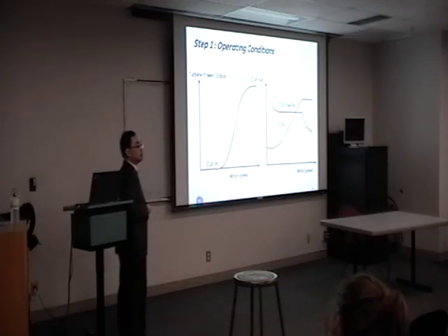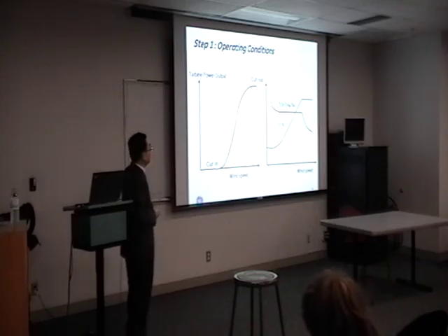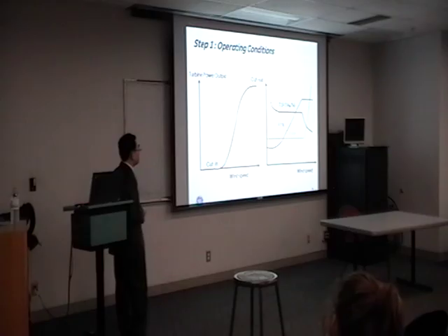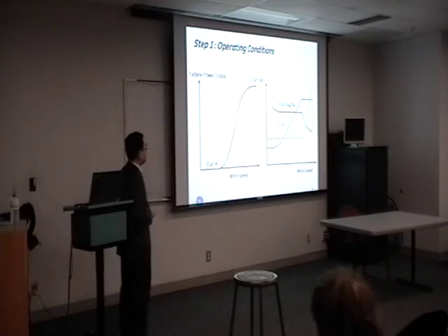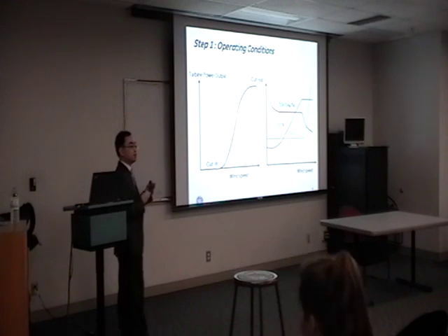Here is another important parameter, called tip speed ratio, which is simply the ratio between blade tip speed and incoming wind velocity. In the linear region of the RPM, we have a constant tip speed ratio. This tip speed ratio is very important in terms of the power coefficient. And this is the pitch angle. The pitch angle remains constant up to a certain wind speed. At very high wind speed, we need to increase the pitch angle because we want to avoid flow separation. That's what I discussed earlier.